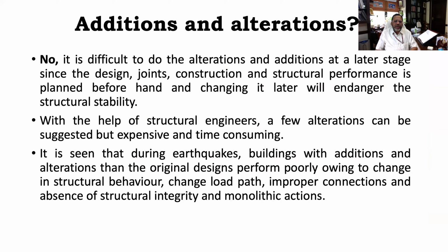So you have to cut the shear wall, and the moment you start chipping off or cutting the shear wall, the dynamics of the structure change, the load transfer pattern gets changed, and that may endanger the structural stability. So it is advised that additions and alterations at a later stage need to be avoided. If at all it is of utmost importance, then it has to be done with the help of a structural engineer, but it is going to be very expensive and time consuming.